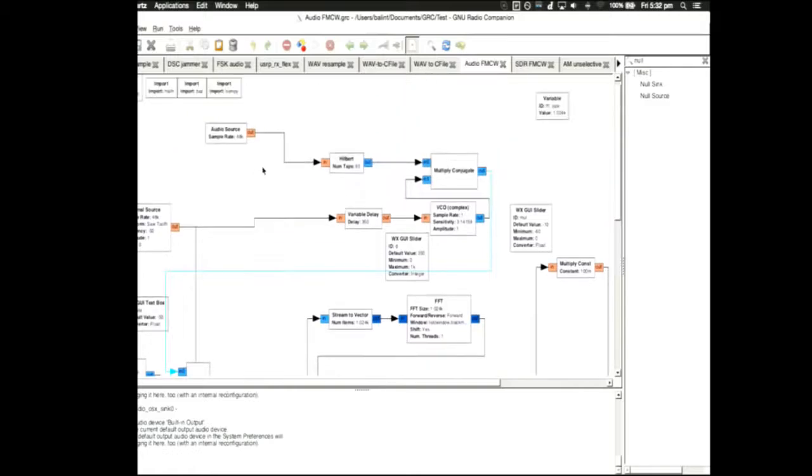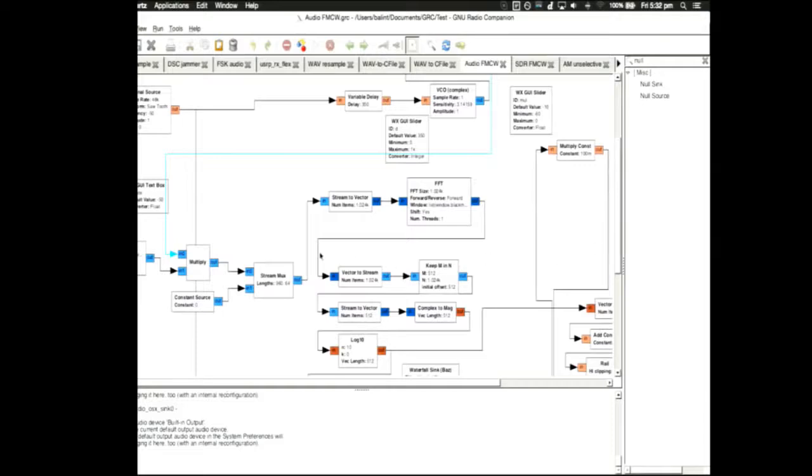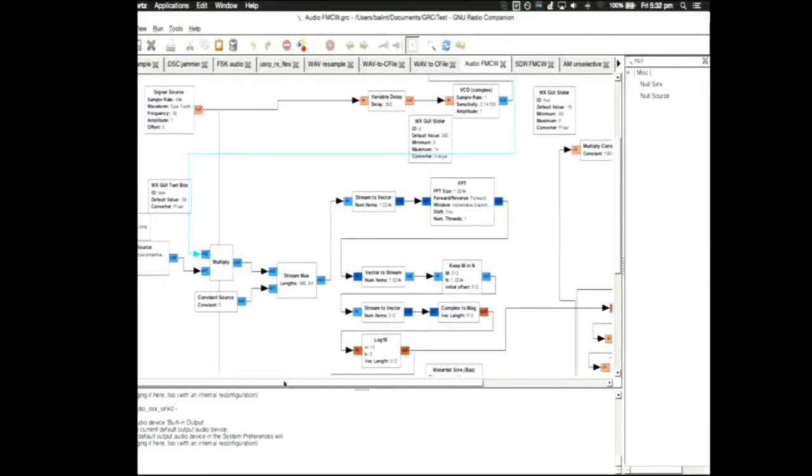So once we've actually multiplied our incoming signal from the microphone by this chirp, we put it into this multiply block. And I've just done a bit of trickery here. I can't even remember whether this is a restriction anymore, because when I do it in Python, I don't worry about it. But I'm trying to do an FFT.